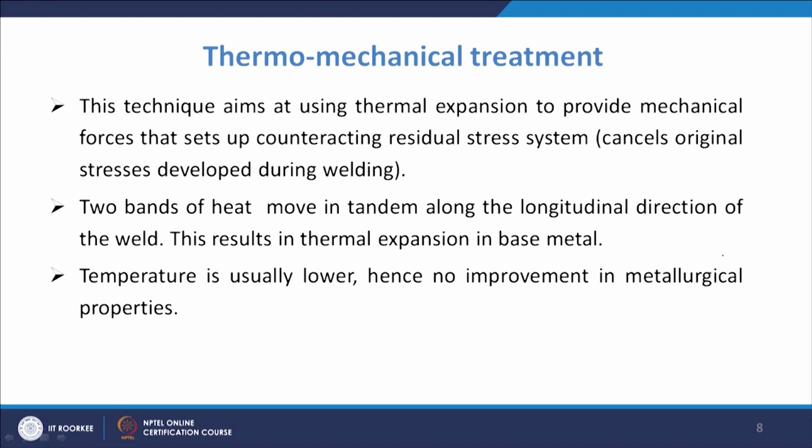Now, coming to the other method, the thermomechanical treatment. Thermomechanical treatment is basically aimed at using thermal expansion to provide the mechanical forces that set up a system counteracting these residual stresses. So, there will be cancelling of the original stresses which are developed in the material.